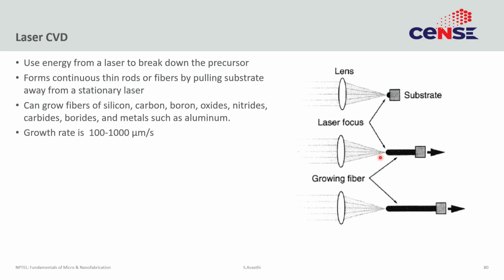You can also do something very cool, which I personally find very interesting, which is laser CVD. You can provide this energy through radiation, so in this case optical radiation. Not very useful for growing films on large substrates, but if you want to grow a wire, laser CVD is sometimes used. The growth rates can be fairly high.